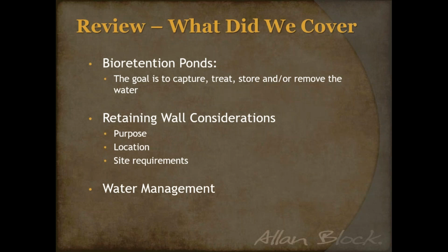And then it all boils into the best practices approach for water management, making sure we're doing everything we can to ensure water does not build up behind that wall. So we try to minimize the potential of having bioretention ponds above the wall. We want to get those located below the wall. And once they're below the wall, we need to know the high water mark, so you know where your drain and your drain rock or your wall rock goes with that fabric.